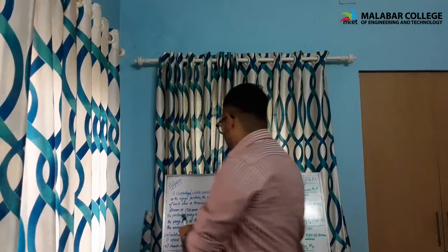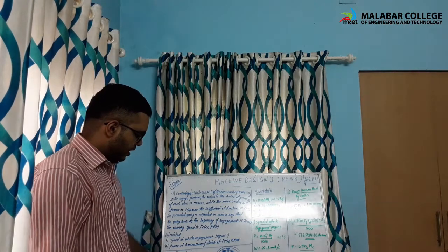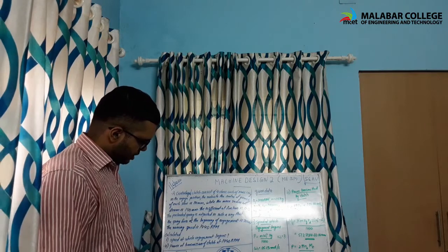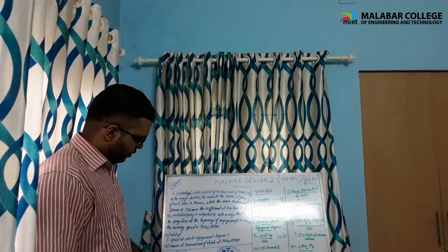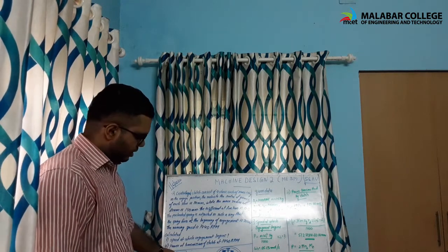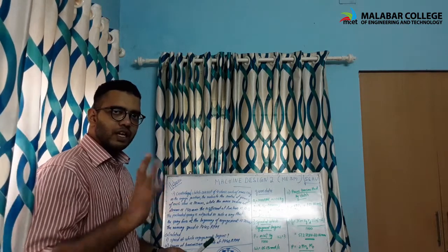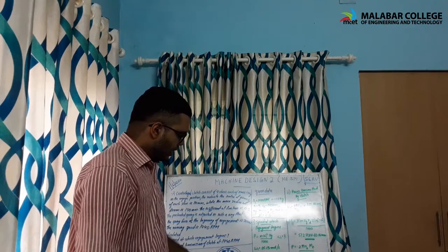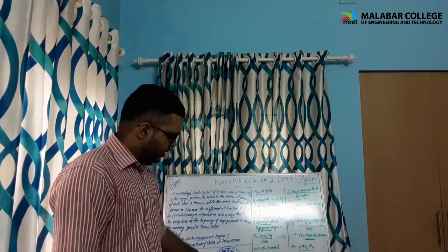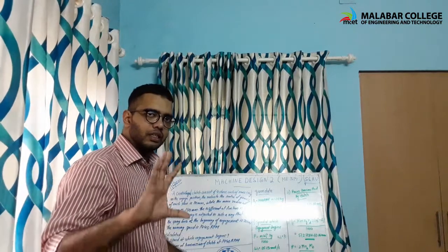And here is the figure, the side view of the centrifugal clutch. We can see one shaft and another shaft, and the loaded springs. When one shaft rotates, the spring experiences centrifugal force, and it touches, and the other shaft will be rotated. N1 and N2 will have varying speeds. This is the cross-sectional front view, and we can see the drum and 4 shoes, and while it rotates, the inner part will stick with the outer drum using the centrifugal force.